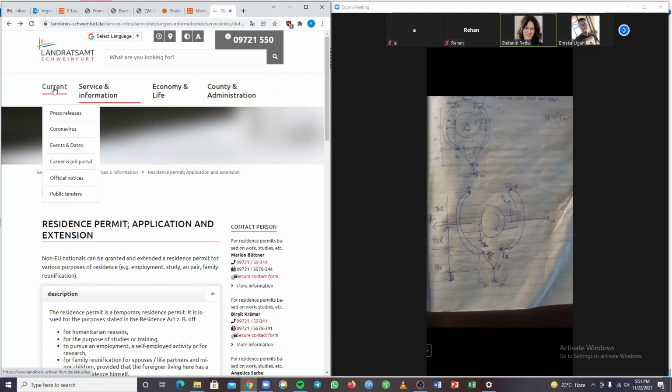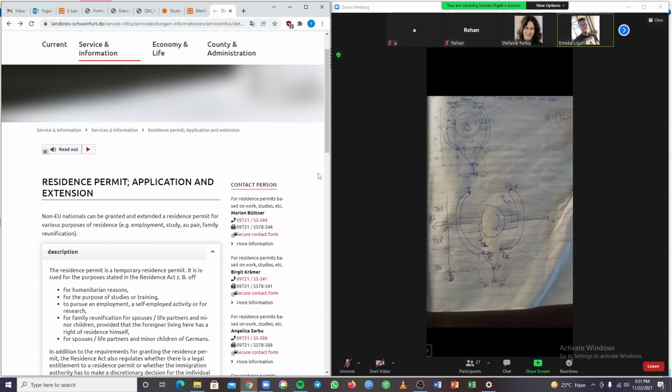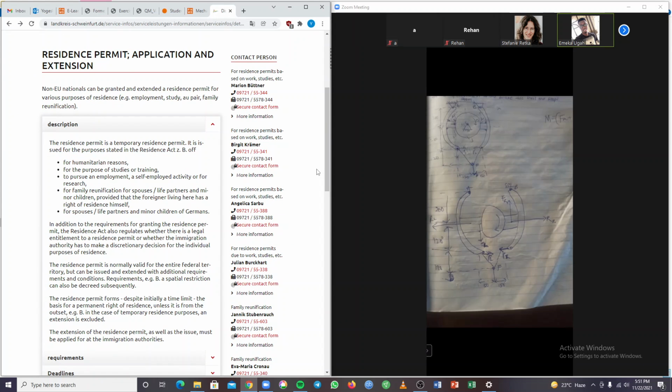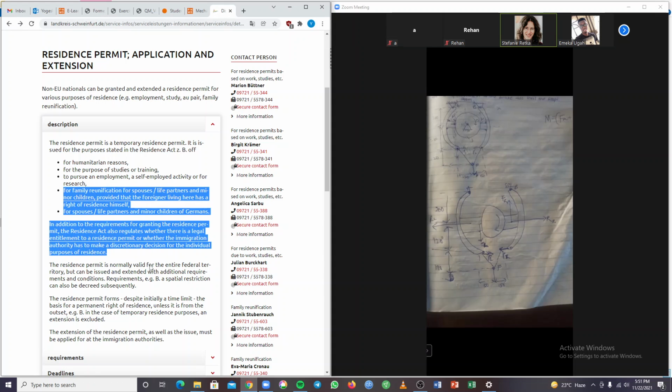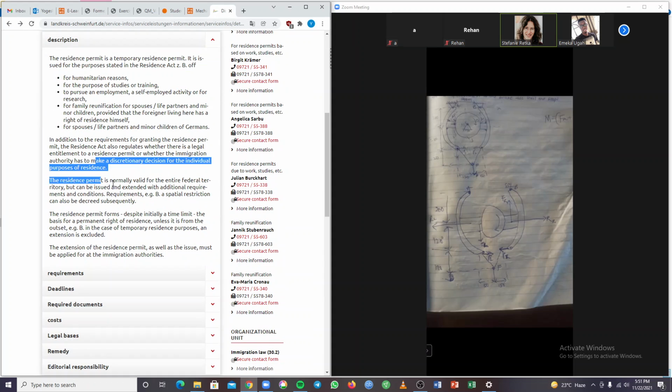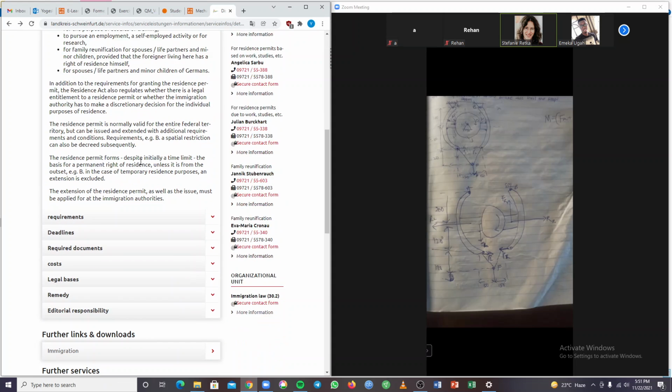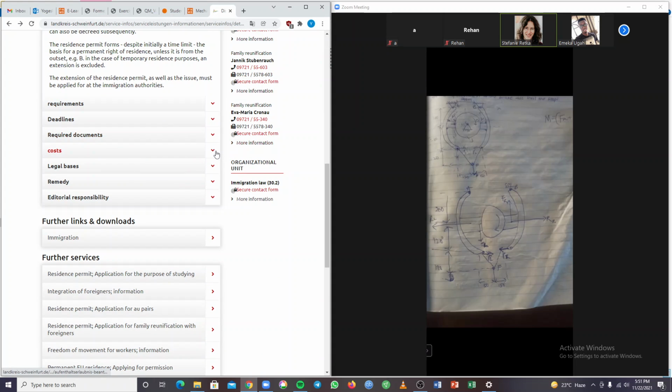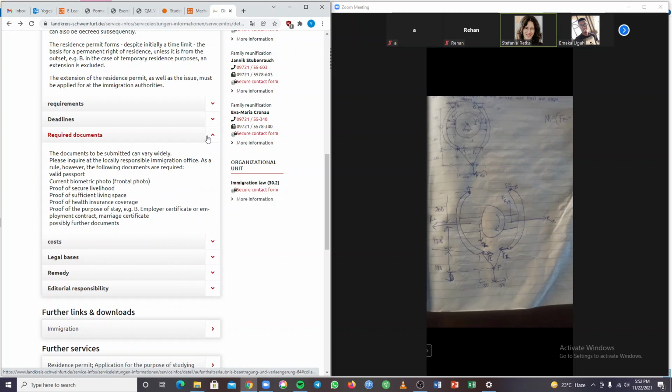I remember from you, do you remember from statics how to draw free body diagrams? Yes, yes. Okay, but it's not correct what you did. Oh. Because there are several mistakes. If you cut through a hinged support, you see the forces, the support reactions. So you have to draw the support reactions in your free body diagram. If you do not cut through a system, you do not see any forces.